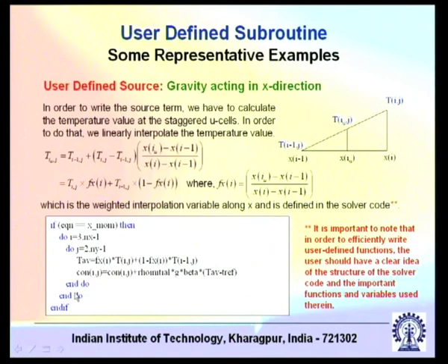Then we are writing con, which is the constant source term, like Sc plus Sp phi_P. That Sc we are calling con. So con I comma j equal to con I comma j, that is whatever was initialized, plus rho initial, that is the reference density, into g into beta into (T average minus T reference). That is how you simply implement the natural convection.